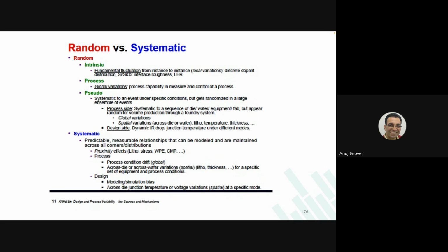When we were talking about clock jitter, or clock variations, we said that due to IR drop or something, there will be a drop that will happen here. And therefore, the clock can arrive a little early or arrive a little late. Now, is this a random variation? You know the physics of it entirely. And if you know the stimuli that is going to activate my particular network, you can also estimate the kind of things that would happen. They are systematic variations, but still random.